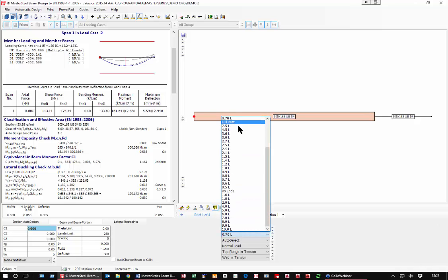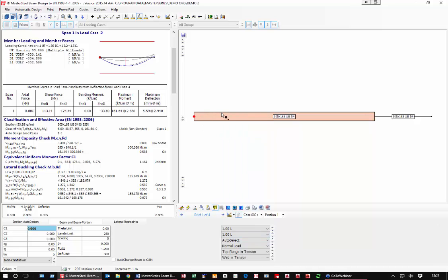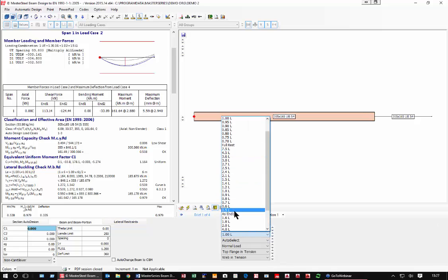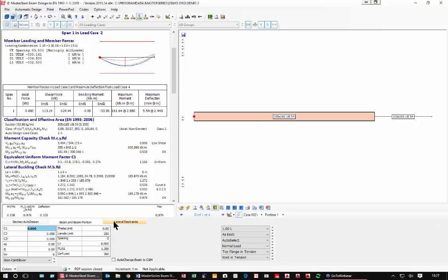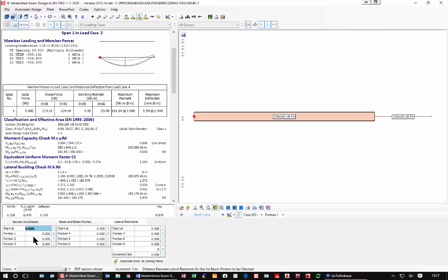If we want, we can then introduce intermediate restraints instead. So if we had joists or purlins or whatever along this member, the alternative is to come along and say we work with 1L, which is normally as per end 1, to keep it simple, and then we say, but we have restraints at 1.5 and 1.8 and 2 meters.